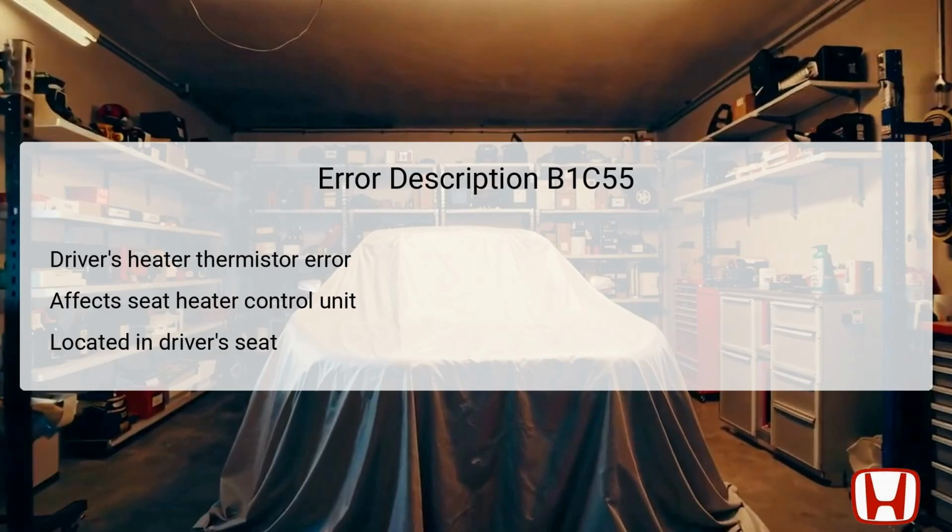If there is an open circuit in this thermistor, it will prevent the heater from turning on, leading to discomfort for the driver during colder conditions. It is crucial to identify and resolve this issue to ensure the proper functioning of the heated seat feature.